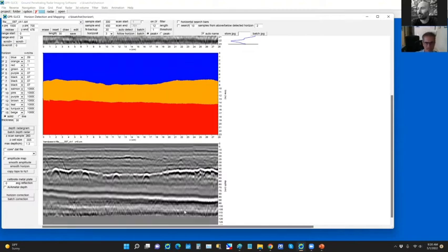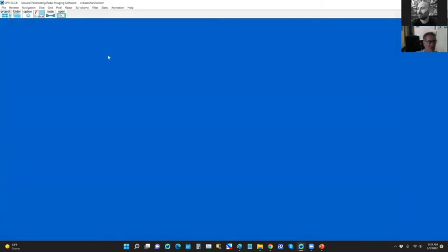So if you notice, the bottom layer is variable, it's not flat. In this particular data, which is the info depth radargram, there's no time in this. This has all been converted to depth, so having a time scale wouldn't mean anything. You have options where you can run some of these features in batch and actually adjust all your radargrams to actual depth.